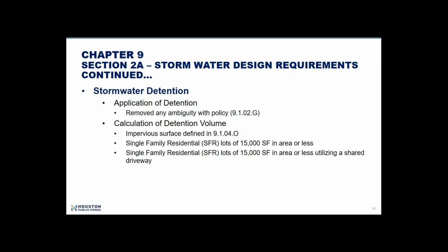And so we see this a lot in our work here at the city when it comes to private development now. The townhouses, various other things cropping up, 3 or 4 townhouses going onto a lot, then they use a shared driveway. And so we have this discussion with owners and engineers a lot. This conversation is just about the detention requirement. There are other issues we'll get into in other chapters, particularly water and wastewater, that impact these developments as well. But this one just focuses on the detention rate.